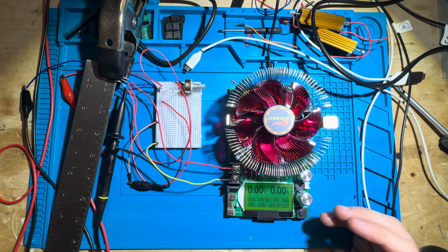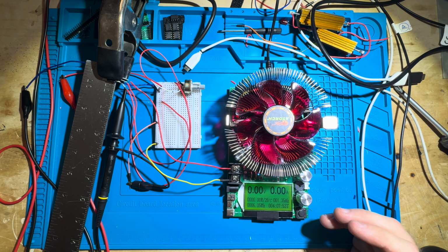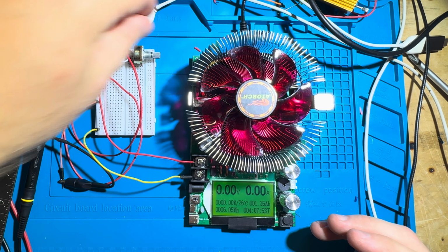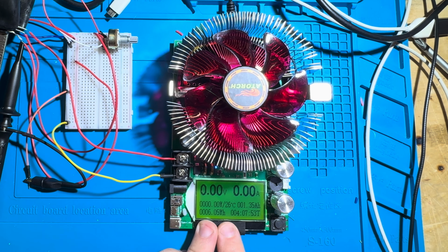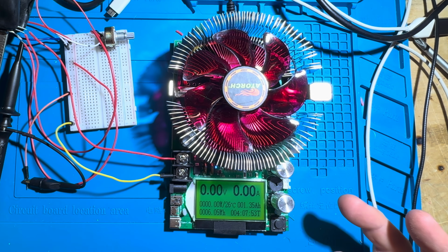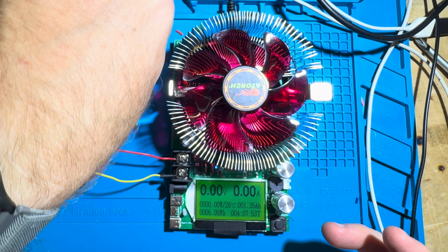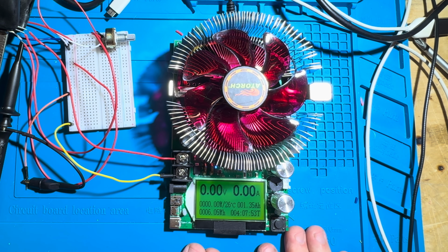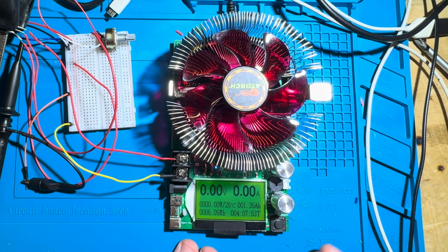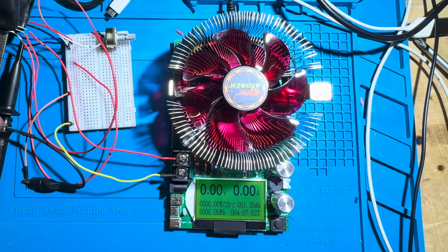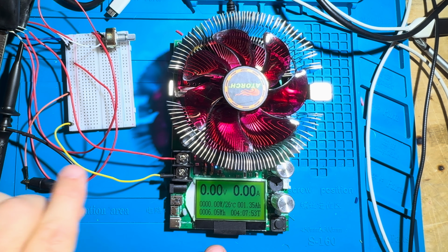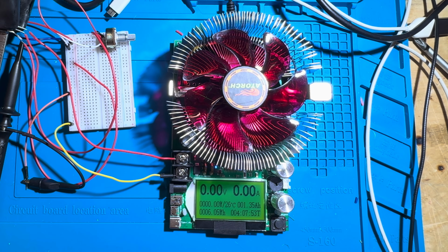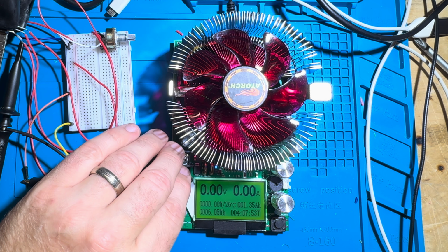So I'm going to turn this on, and we've got 12.997 volts across the MOSFET. And notice we're registering 0 volts right now. So we're going to start out with a gate voltage at 0. This potentiometer is turned all the way down. And I'm going to slowly ramp it up with no load across this variable load. So I've turned the load all the way down to 0. And we're going to just see what happens to the voltage that we see across this load. Remember, we've got the MOSFET in series with our load here.